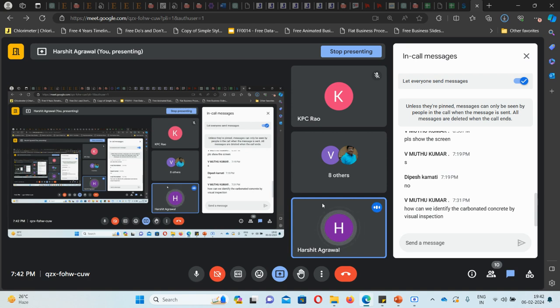So based on the distress that you see on the surface of the concrete, you can guess the possible reason behind the distress and which testing I need to do. Like when there is corrosion, you see longitudinal cracking along the reinforcement direction. If you see that cracking, you can predict what can be the reason behind that, and then you can evaluate whether it is true or not.